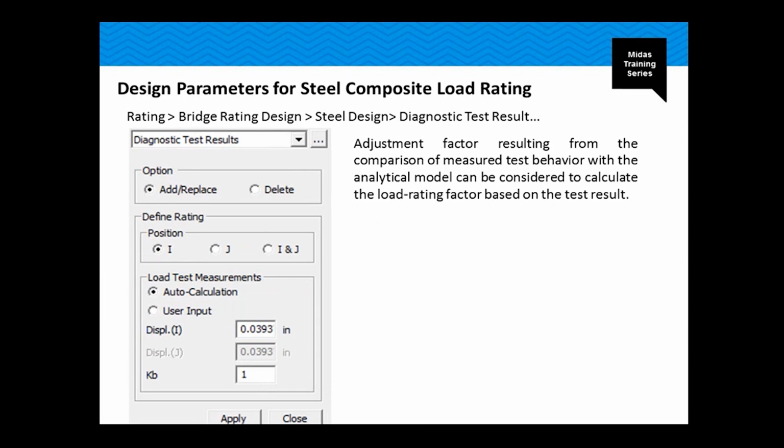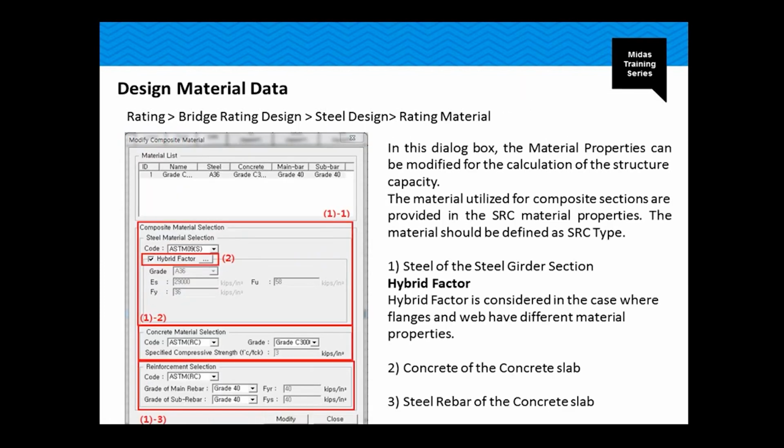Then we have something called diagnostic test result. Adjustment factor resulting from the comparison of measured test behavior with the analytical model can be considered to calculate the load rating factor based on the test results. So you can tell the program here the diagnostic test results that you have measured, and the program is going to take that into consideration for the load rating.